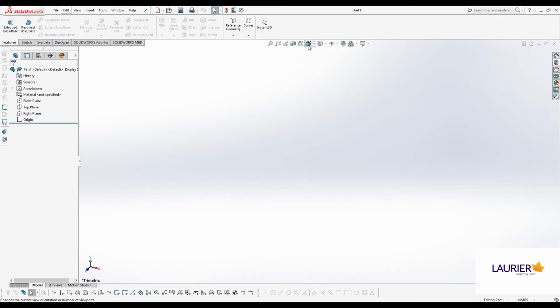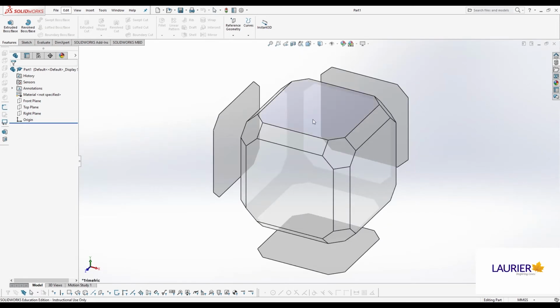It's the cube. If you click on that, it will open up this see-through cube. Your object will be displayed in the middle of that cube, and whichever side of that cube, whatever facet of that cube that you click on, as you'll see in the preview to the upper right, will be rotated so that it's oriented such that you're looking normal to that face that you clicked on. It will reorient the part very accurately.